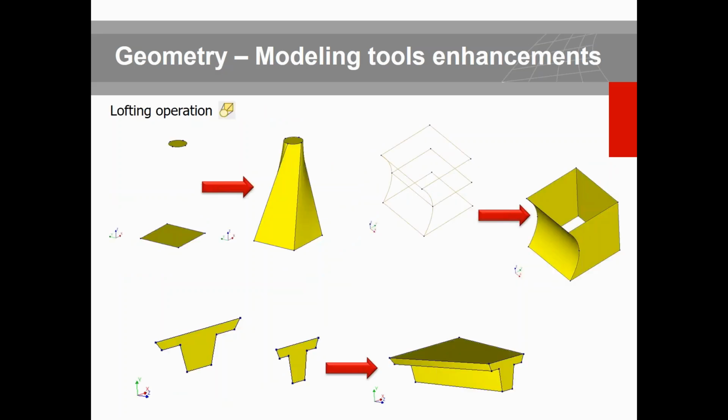In addition to the sweep, we have a lofting operation at the geometry level, based on different criteria and methodologies, that helps you come up with a complex shape from minimal reference geometry. You can generate your model in a three-dimensional environment and proceed with your analysis. This could be a double arch dam, or some sort of twisted and tweaked shape that you may consider in your model.